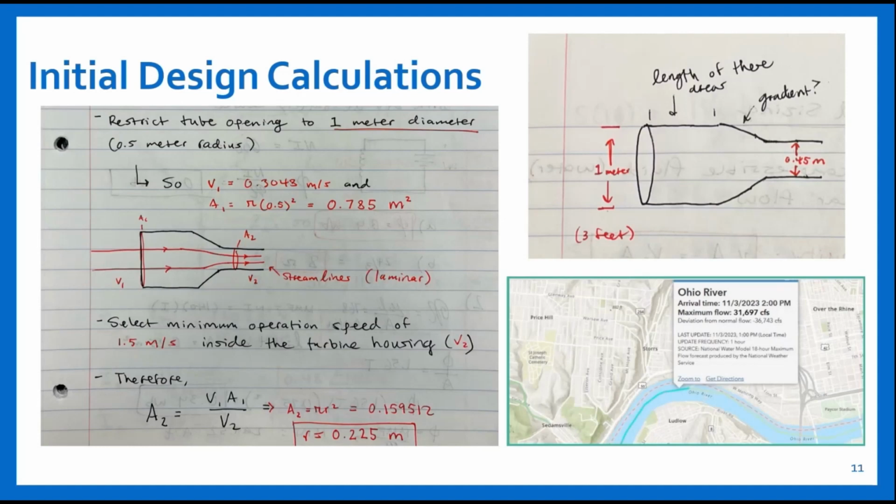And then we used ArcGIS, which is provided through UC, and connected to the USGS streamflow model to figure out the worst case spots that we could look at on the Ohio River. We got around 1 foot per second, which is about 0.3 meters per second, and decided to base it off of that. It should be noted that there are definitely better parts of the river to deploy than the one we selected. Where the river gets narrower, it speeds up. So there are some good places by North Bend that might be more feasible.